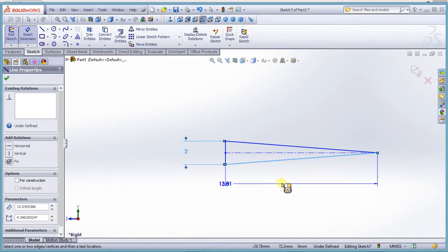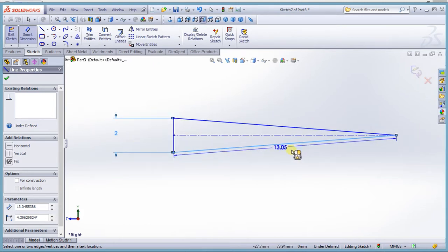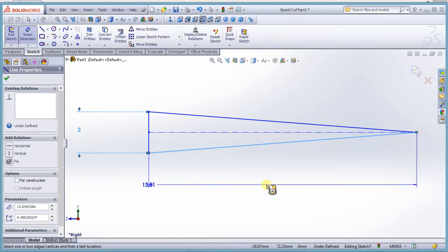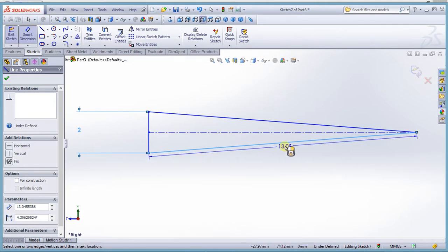Don't take it down vertical, horizontal like this. Slant it. Measure it by that slant height. If you pick your smart dimension, just at that point from the line, don't extend it much, because if you extend it much, it will take a horizontal distance, and that is not where we want to measure it. You want to measure it with that slant height. Just immediately the line, you have that slant height where you have 18.0.